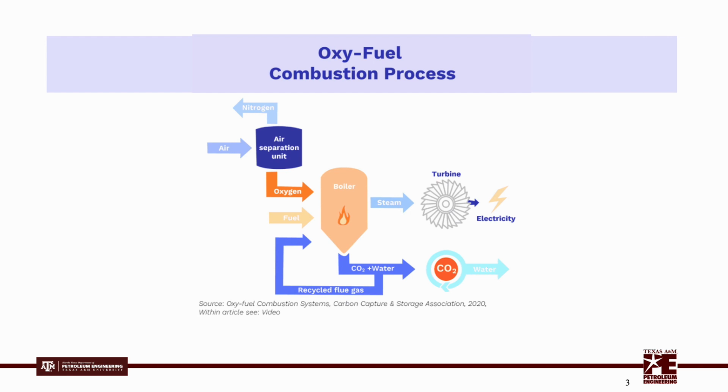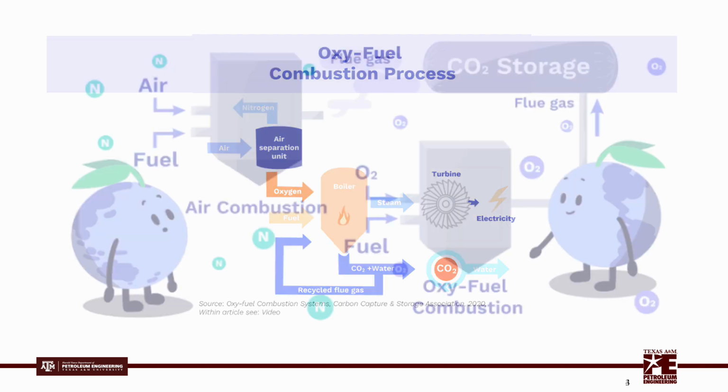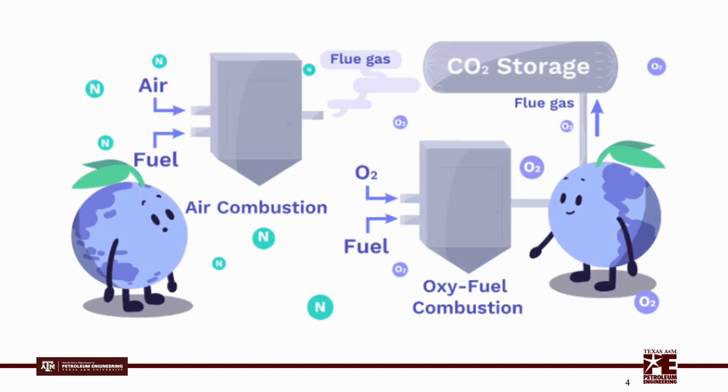It is then combined with a fuel, usually either coal or natural gas, into a stream of carbon dioxide inside a combustor. The fuel and O2 chemically react, and the resulting CO2 and H2O steam pushes a turbine that generates power. A major benefit of the oxygen-rich combustion is that it also results in pure CO2.